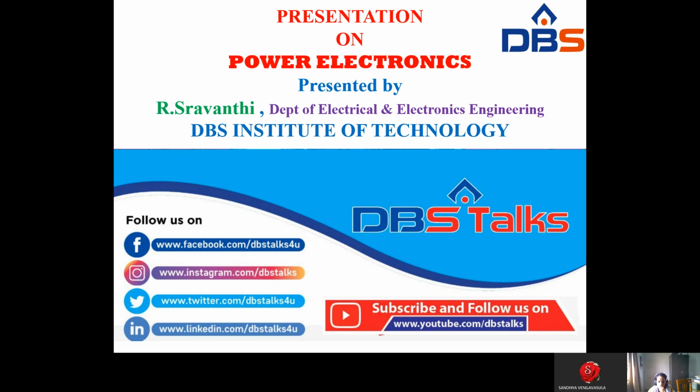So single phase half wave converter with RLE load. Half wave control means here two thyristors and two diodes will be there. This is a freewheeling diode and this is a load. Okay. So at starting we give a pulse to T1, then T1 D1 will operate, and whenever we give a pulse to T2, then T2 D2 will be operating. Okay, so now we have to see the waveforms.